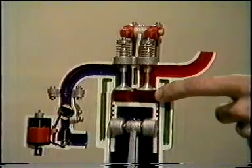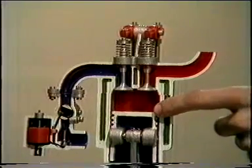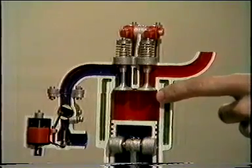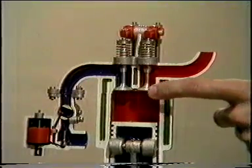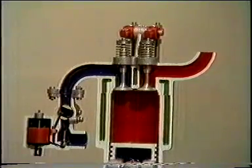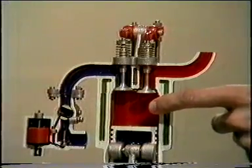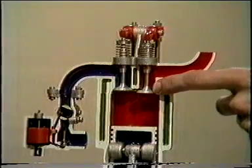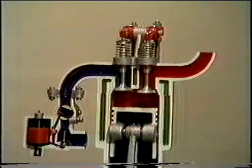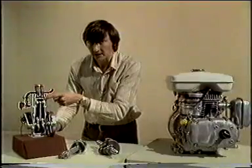That's the compression stroke. And on the third stroke, the piston is actually forced down the cylinder by the gases which have been ignited by the sparking plug and are now expanding down this space. On the fourth stroke of the piston, it comes back up, forcing the spent gases through the open exhaust valve and out eventually into atmosphere. And it's at this point that we are actually going to do our dynamic analysis.